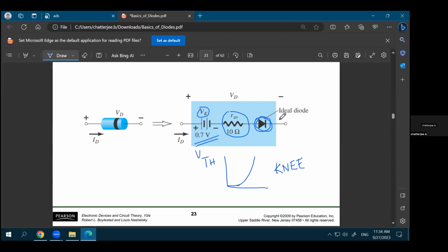I was wondering, I'm not sure how you get to the DC point of the output. Okay, so as you see, the minus is clear, right? If this is 5 volt, because of the virtual ground property you have this at 5 volt as well. Generally the op amps are designed in a way that if you are connecting them in feedback, for example if you connect this one and this one together, and the DC voltages are different, it will create a DC current flow through the op amp, right?